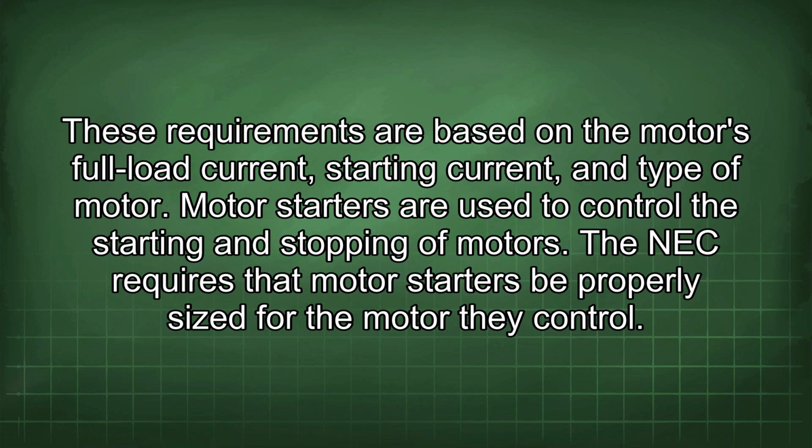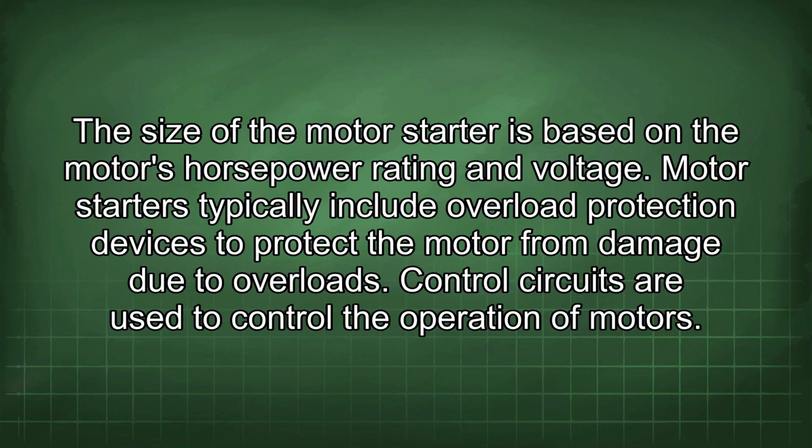Motor starters are used to control the starting and stopping of motors. The NEC requires that motor starters be properly sized for the motor they control. The size of the motor starter is based on the motor's horsepower rating and voltage.